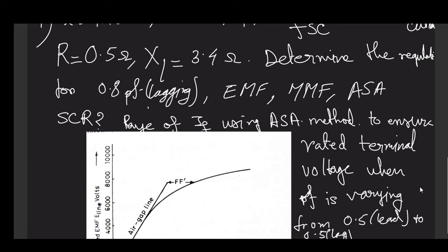The essence of this problem is that a magnetizing current, leading power factor, tends to give negative regulation. That means if you want a constant voltage, you need to decrease the field current flowing through your field winding.